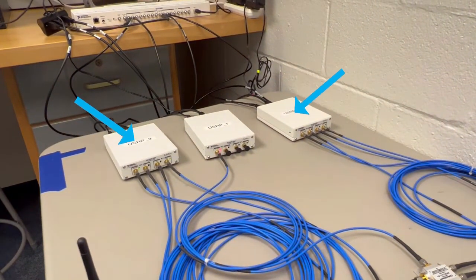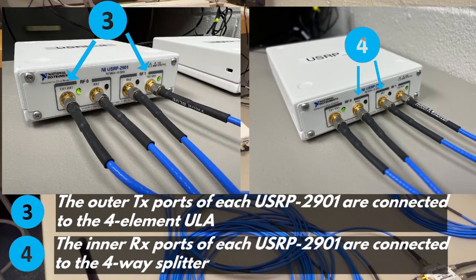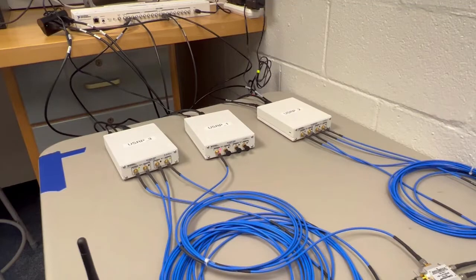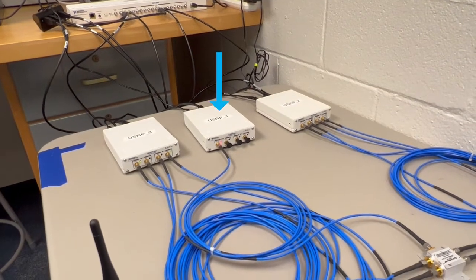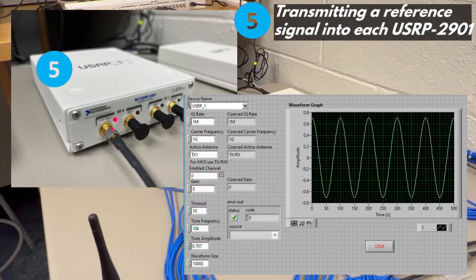The outer USRPs are responsible for receiving signals at the ULA as well as the 4-way splitter. The outer RX ports marked by the green indicator light are connected to the ULA, while the inner RX ports are connected to the 4-way splitter. The center USRP is used for transmitting a reference signal into the 4-way splitter. The LabVIEW code for this USRP is exactly the same as the transmitting end of the hardware testbed.